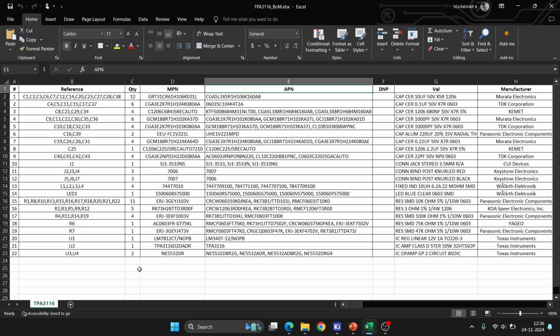That is very important because you selected one part number. If this part number goes out of stock or it is not available online, you can choose the alternative part number, then you can put it on the same. Always keep this as a habit whenever you are designing a PCB. If you are choosing an MPN, always keep at least one alternative part, and then do not populate.